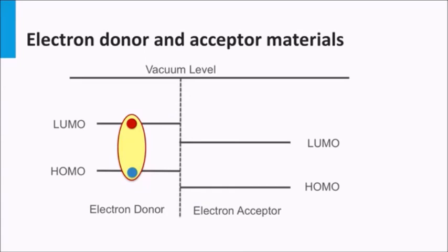Light excitation results in so-called excitons, which are excited electron and hole pairs that are still in a bound state due to the mutual Coulombic force between the particles. The exciton can diffuse through the material. These excitons have a low lifetime in organic materials. They recombine back to the ground state within a few nanoseconds, meaning that the diffusion length of such excitons is in the order of only 10 nanometers.